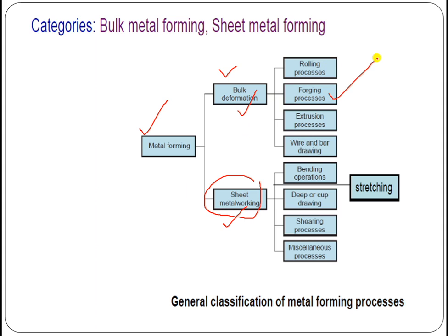Forging is a forming process in which the plastic deformation of the material, that is a red hot billet, is done with the help of forces from the punch of the forging press. Rolling forms things like galvanized iron pipes, which are formed with the help of the rolling process, again a forming process. Extrusion: copper wires and mild steel wires used in various agricultural and industrial applications can be formed with the help of the extrusion process.